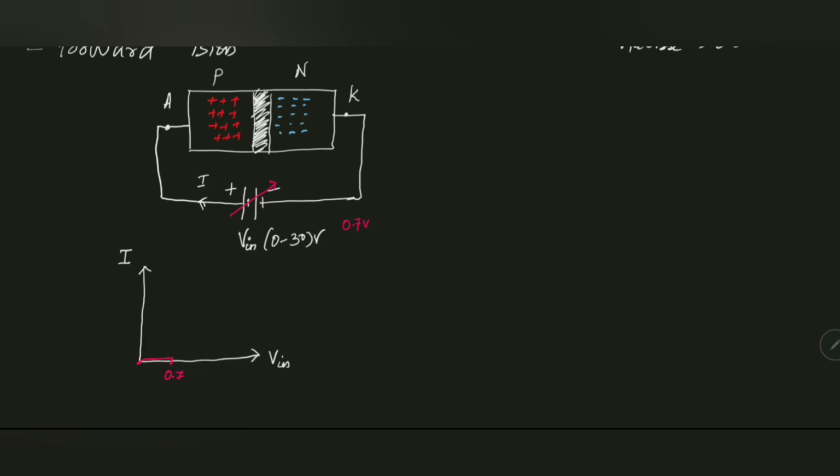And to remember this, when the p-type layer is connected to the positive of the battery, it means that you're supplying more and more positive charge to the p-type. Initially, before applying the voltage, the numbers of positive and negative charges in the p-type will be the same, and similarly in the n-type region the number of electrons and holes is going to be the same. It's kind of neutral. There are no free electrons because these free electrons have already diffused into this layer.